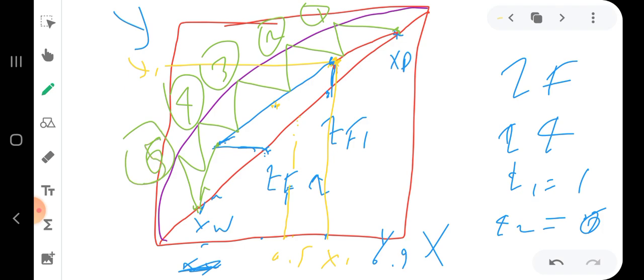Okay, and if you're interested to know the stage for feed number 1, you see the Q line for feed number 1. Here is feed number 1, here is the Q line, and it is inside the second stage. So the second stage is the stage where feed 1 is going to be introduced.